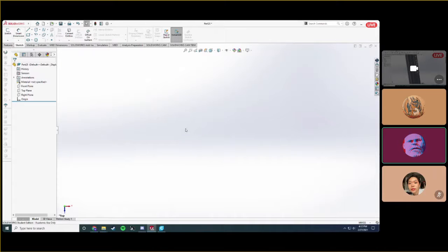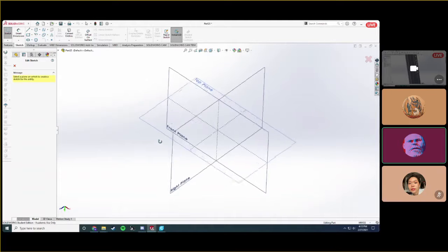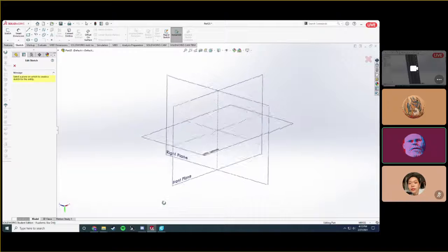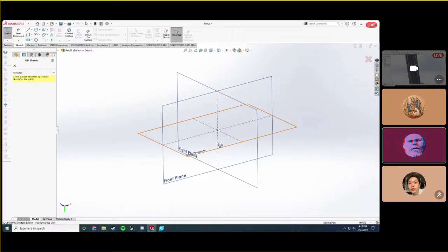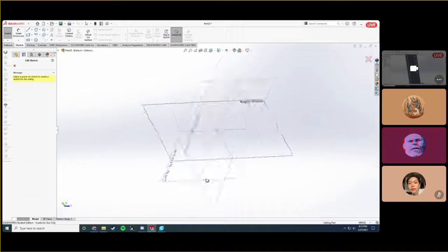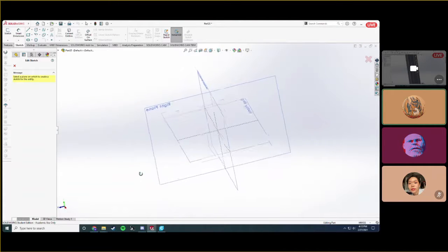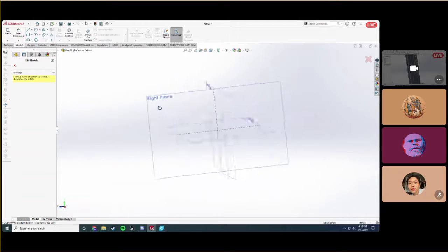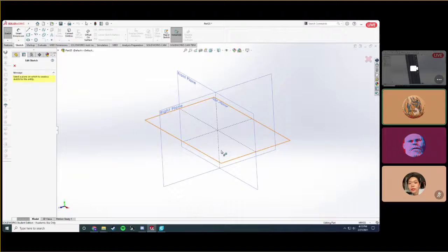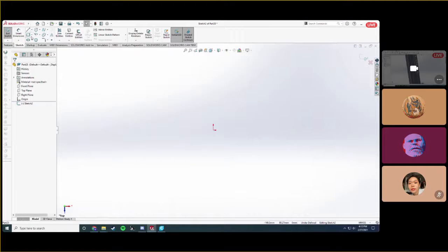The reason why you would define it to be on a certain plane is basically how you want to think about how you're going to import it into the assembly file, and you just kind of want to make it easy on yourself so you don't have to rotate it as much based on how you define the body. You have to go into a design thinking of how it's going to come out. Like I could just orient this little thing right here, which is what I'm looking at when I'm spinning it, just to make it nice. You could just do the top plane here.